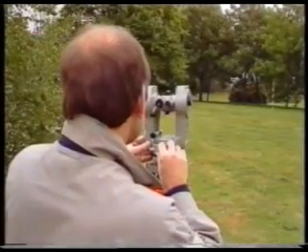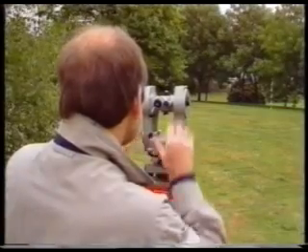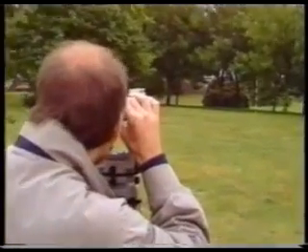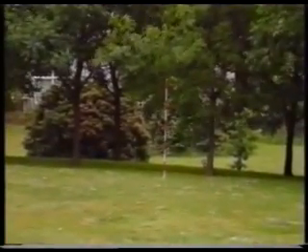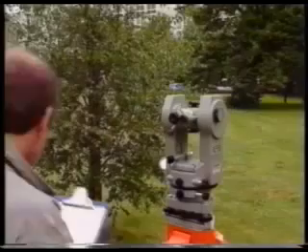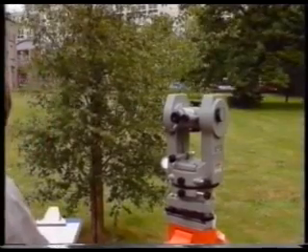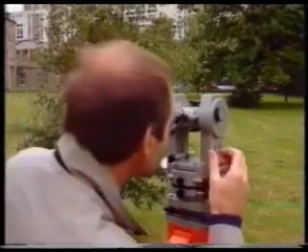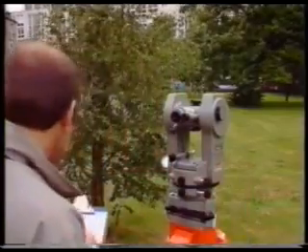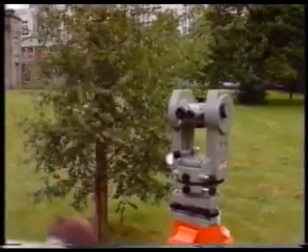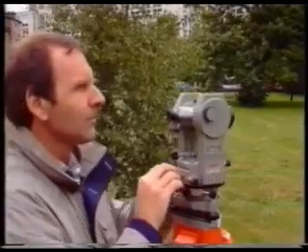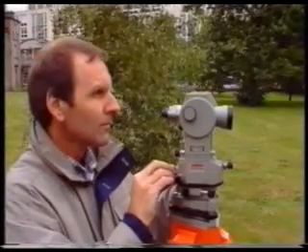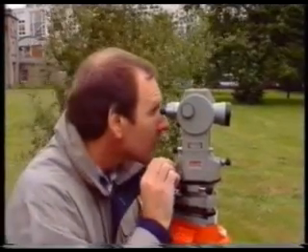Once the theodolite is correctly set, and before any of the points of detail are fixed, an observation is taken to another control point, B. The horizontal circle is read and recorded. This establishes the orientation of the circle and is used later when plotting the detail points on the plan. Having established the orientation of the horizontal circle, the staff is sighted.